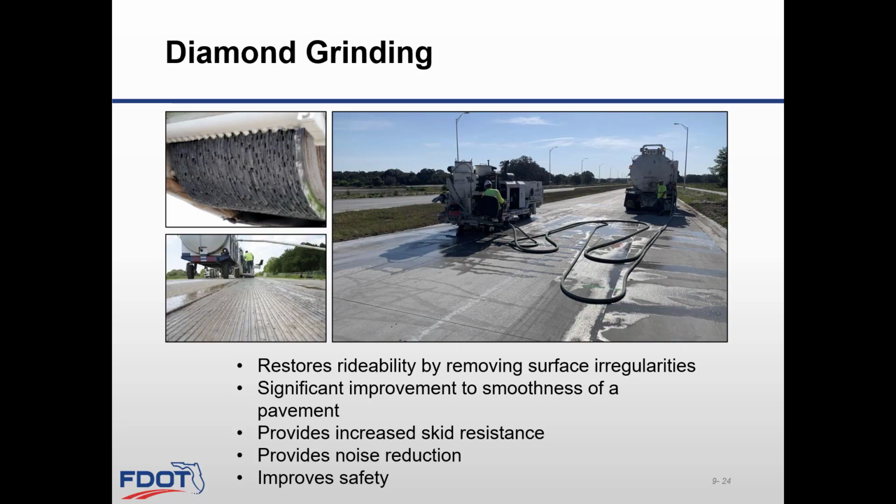Once the slab replacement activities are finalized, diamond grinding can be done on all the slabs for the project limits. Diamond grinding also helps remove surface irregularities such as faulting when it's less than ½ inch, improves the ride and results in a quieter road. This operation is done before you clean and seal all the joints. More information can be found in Standard Specifications 352.